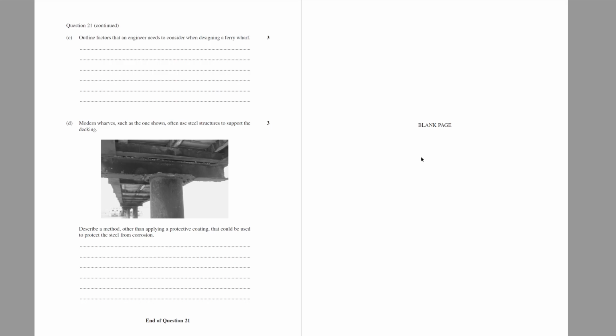So what you've got to think about is, okay, you're going to build a wharf. What are the considerations? You don't put a wharf in the middle of nowhere, you put a wharf near something. So you think about the needs of your users, where the traffic generators are, and the safety. You think about the depth of the water to make sure the boat's not going to come up on a sandbank, run ashore, run aground, right? So straight away, I want to make sure that it's somewhere safe, somewhere useful, and somewhere functional, right?